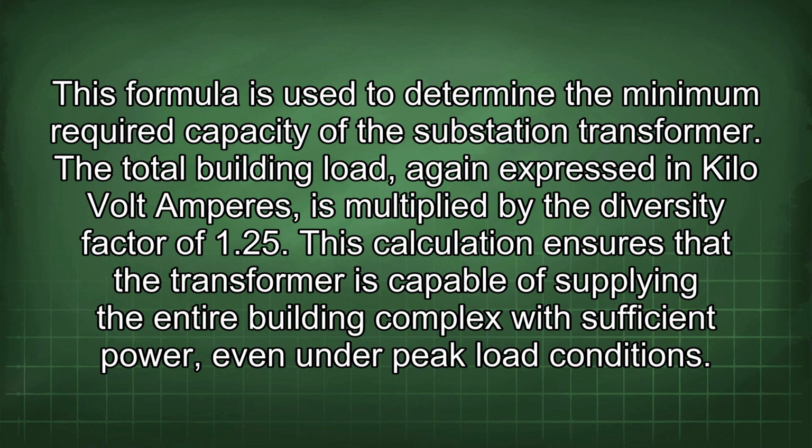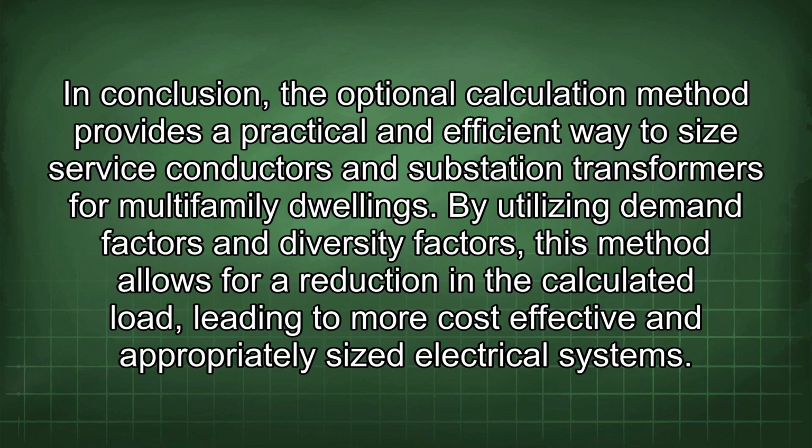The total building load, again expressed in kilovolt amperes, is multiplied by the diversity factor of 1.25. This calculation ensures that the transformer is capable of supplying the entire building complex with sufficient power, even under peak load conditions. In conclusion, the optional calculation method provides a practical and efficient way to size service conductors and substation